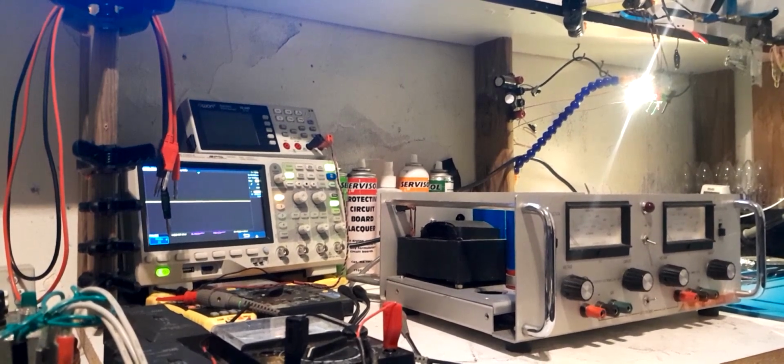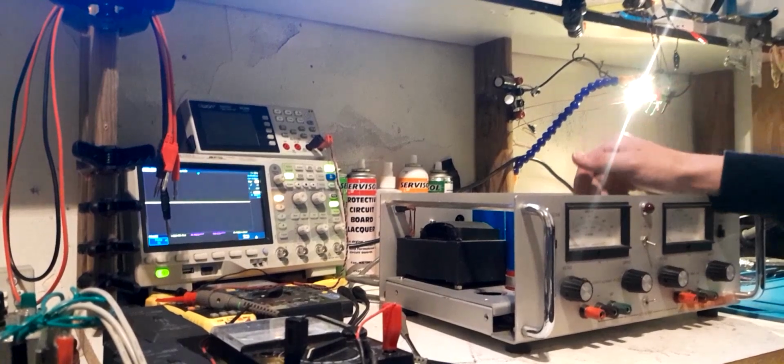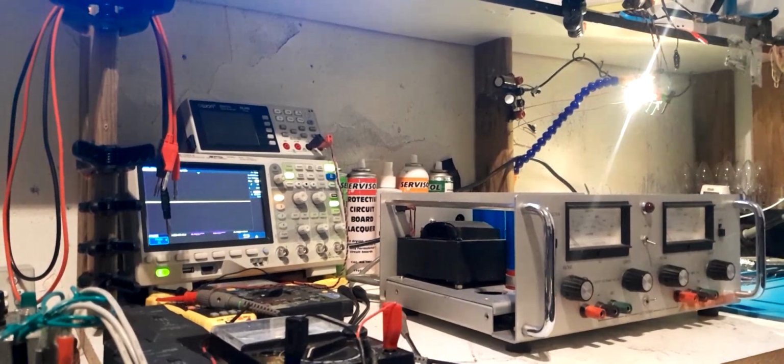Now, I think what I'm going to do is take out one of the references, the same one that we've taken the caps off basically, and put a zener in there, see if there's still oscillation, because then I'll know if I've got oscillation coming from the op-amp circuitry getting fed into the reference, or is it actually the other way around, the reference is oscillating and it's getting fed into the op-amp.